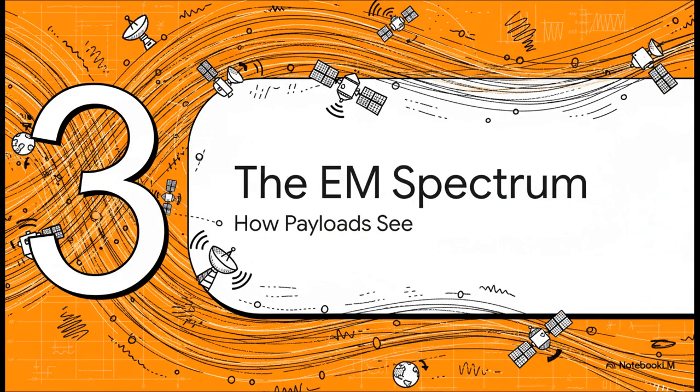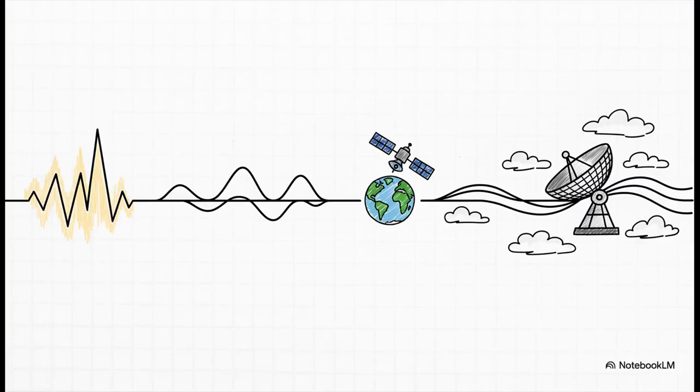All right, part 3, seeing the electromagnetic spectrum. To really understand how payloads see, we need to talk about their ultimate toolkit. Almost all space payloads operate through the electromagnetic spectrum, and the scale here is just staggering. We are talking about spanning at least 16 orders of magnitude, from ultra-short exahertz gamma rays all the way down to kilohertz radio waves that can be kilometers long. Your payload design entirely depends on which exact slice of the spectrum you're targeting.